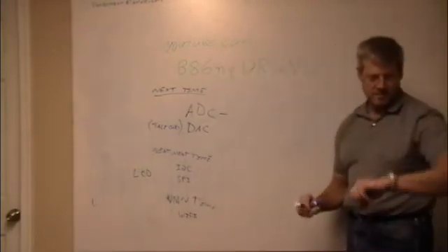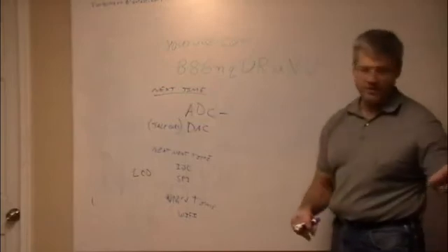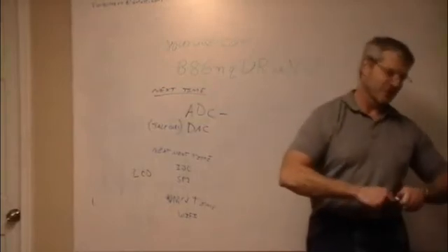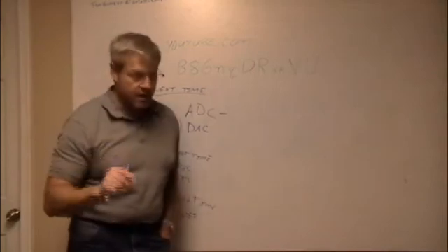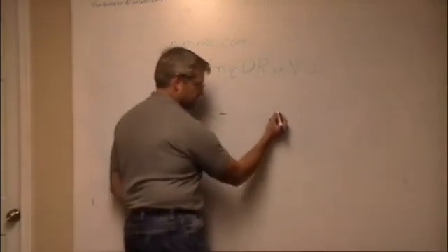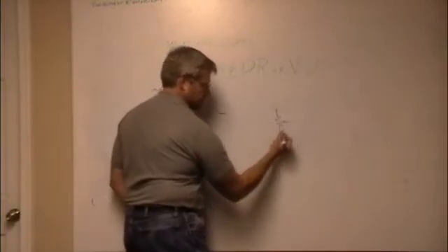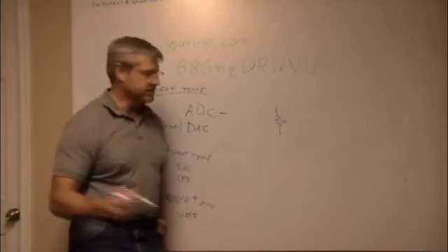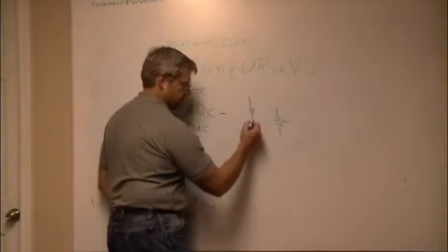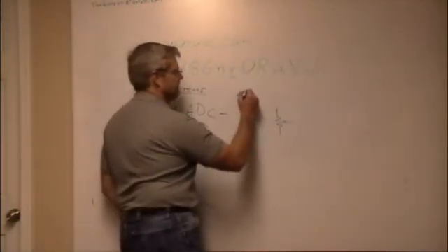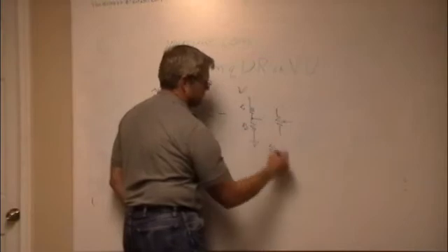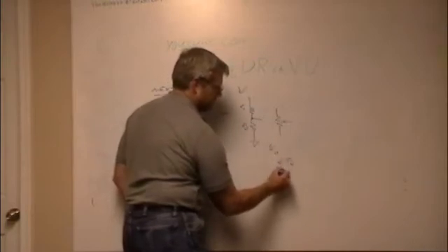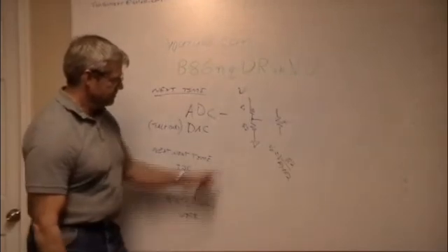Well, and not to get too deep either, but thermocouple versus thermistor. Yeah. So here we go. Okay. A thermistor, which is what most people think a thermocouple is, has a. So if I think about a pot, right, a potentiometer, I would draw it like this. And the very first class we talked about a resistive divider, right? I've got V to ground, I've got R1, I've got R2, V out equals R2 over R1 plus R2 times V. Where's your V out? Right here.